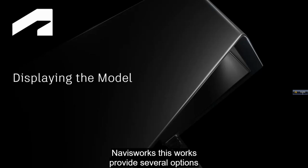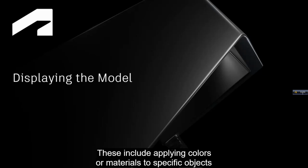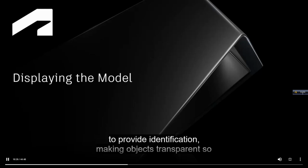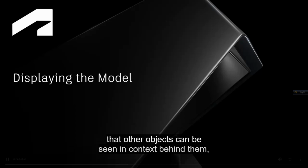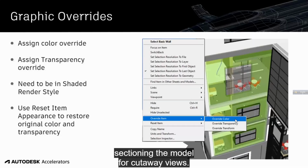Navisworks provides several options for displaying your Revit models that can help communicate the design during a design review. These include applying colors or materials to specific objects to provide identification, making objects transparent so that other objects can be seen in context behind them, sectioning the model for cutaway views.